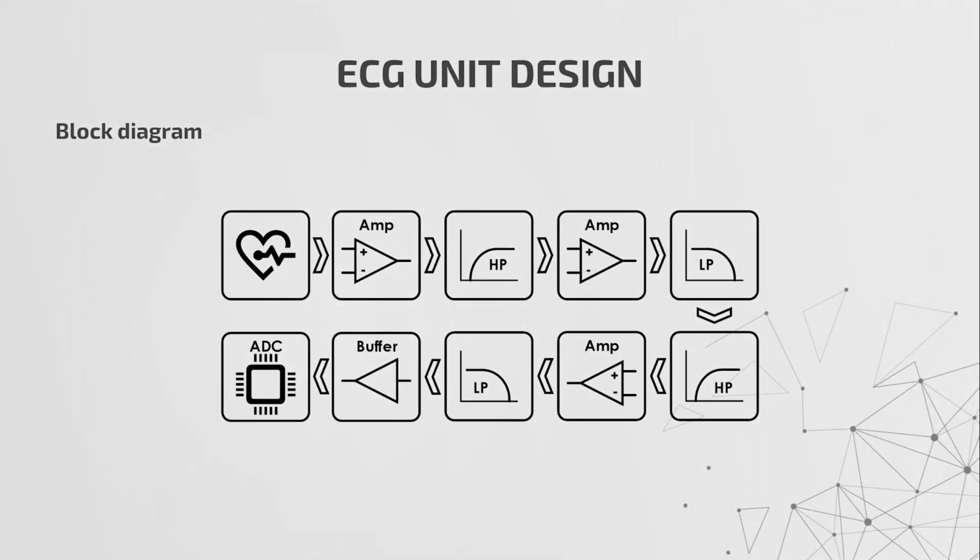According to design, we collect ECG impulses through an infrared LED and a photodiode. The received signal is in millivolt stage, so we need amplification. We followed a multi-staged amplifier design, which is similar to our EEG unit. The total gain of the section is 1000. We have used a 0.7 Hz high-pass filter and a 2.84 Hz low-pass filter in each stage to get a clean amplified signal. After this stage, the ADC will take care of it.